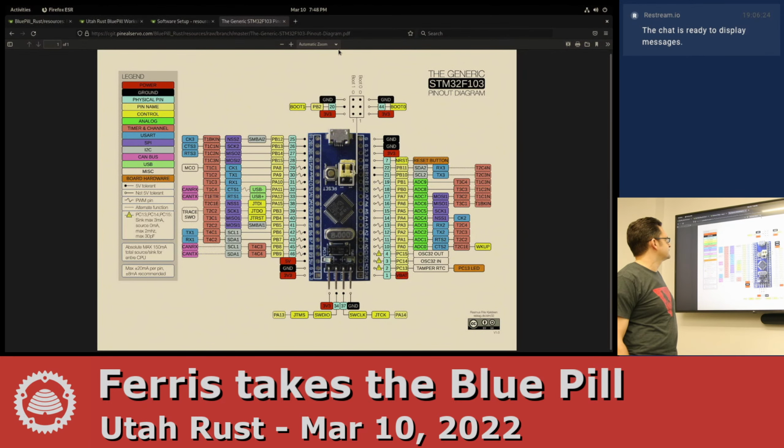And along the side here, we've got pin headers. They're 0.1 inch between centers, which is the same header spacing as your typical pin headers, solderless breadboards, and all sorts of connectors, so it's very handy for doing prototyping.